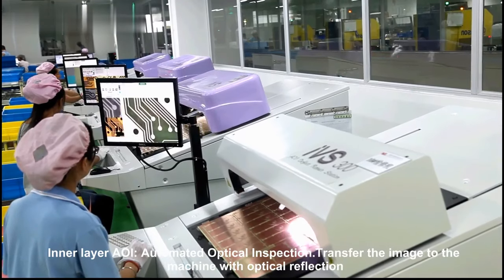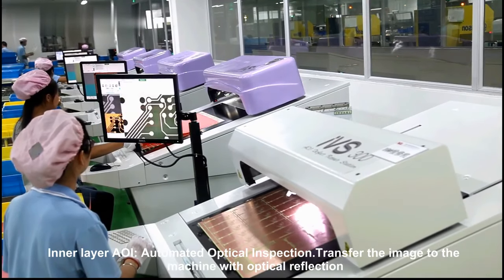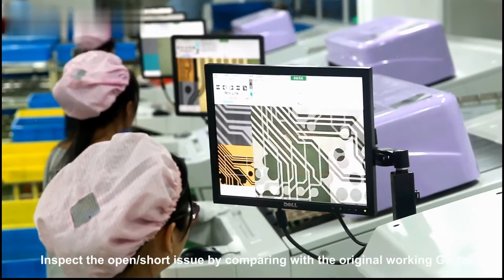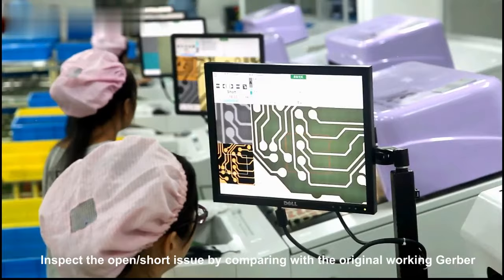Inner layer AOI, automated optical inspection. Transfer the image to the machine with optical reflection. Inspect the open short issue by comparing with the original working Gerber.